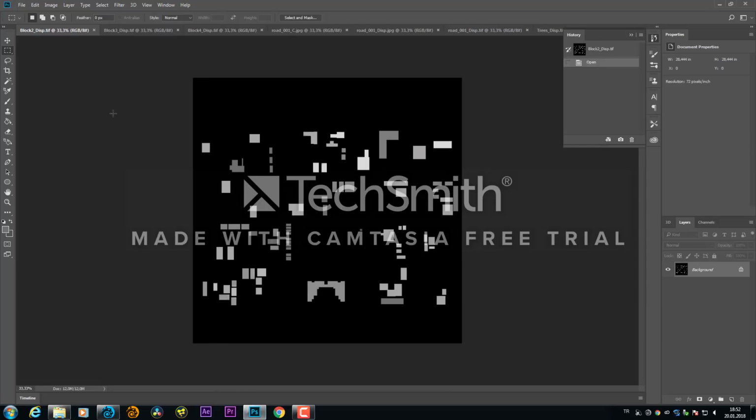I got some images here. These are my height maps. For those who don't know, height maps are grayscale images that actually define how high any object should be. From black to white, black being 0, white being 1, and all the other grayscale images that you put in there define the heights of individual buildings. The white ones are the highest, the grays are lower, and dark grays are even lower, and so on and so forth.